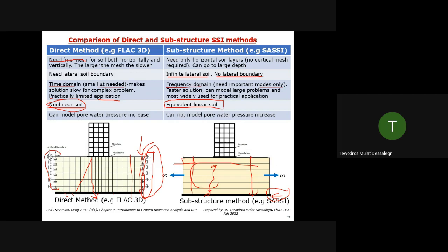It's something like constitutive models, where we are capturing the full hysteresis loop, the tangent of the hysteresis loop at any point. But when you say equivalent linear, it's the secant modulus, the average of the hysteresis loop. Those degradation curves we developed from the secant modulus, which one is this? Is that the linear or equivalent linear?